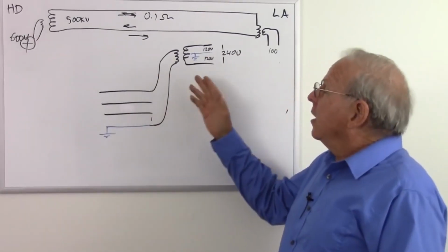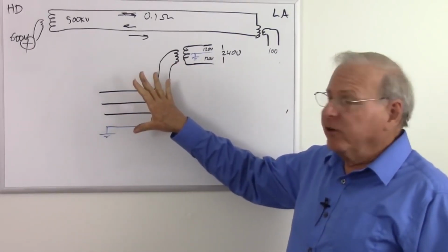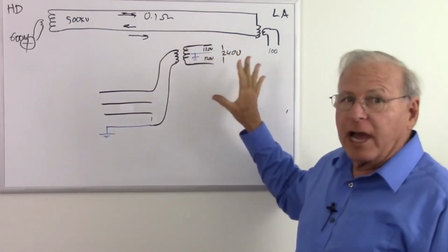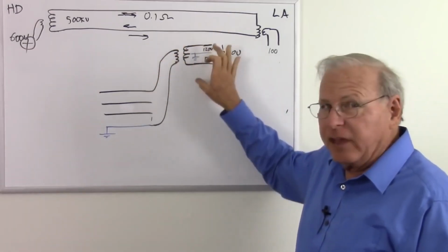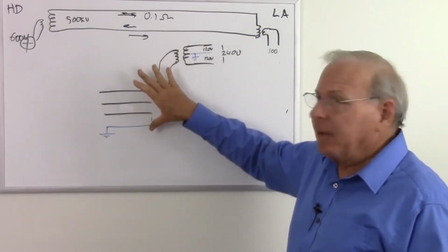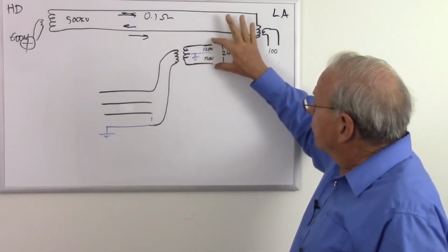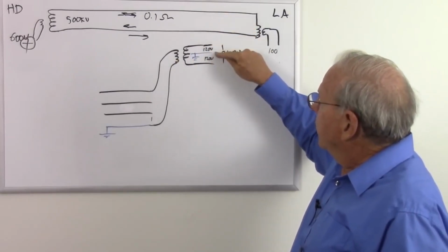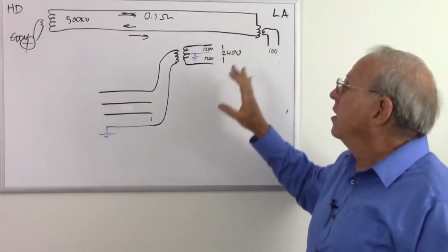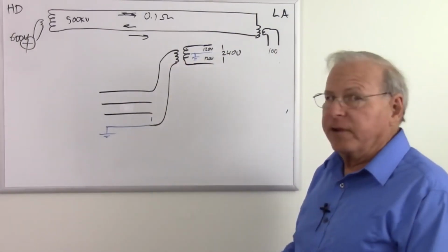Now, I may not be getting the wiring here exactly 100% right. I'm not trained as an electrician or a power engineer, and exactly how they wire them might be a little more like I described for some areas where you get two of the phases, and exactly how they wire the transformer could be different. Maybe I'll cover that in another video, but the basic idea is that most houses are wired with the split phase, 120 to neutral, 120 to neutral, and then 240 across both of the phases, where some are wired with the 208 volt standard I mentioned before, coming directly off the three phase.